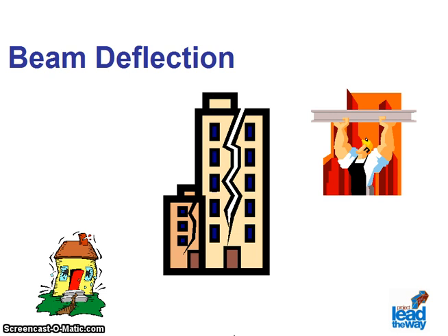However, the major concern when designing a building and thinking about deflection is the ponding of water on roofs. The additional weight of water can cause roof leaks and excessive additional loads. In areas such as the northern part of the country where there are measurable snow accumulations, when the snow melts and the roof drains are clogged, ponding and deflections have caused more than one roof to fail.